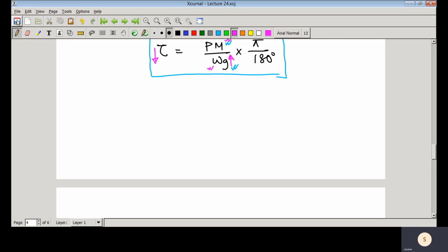And in the frequency domain, to indicate stability as well as performance, we characterize those things in terms of phase margin, delay margin, or gain margin. So phase margin and gain margin come from the frequency response, and percentage of overshoot, settling time, etc. come from the time response. So now we are going to discuss the relationship between the time response and frequency response specifications, and we will do it from the closed loop